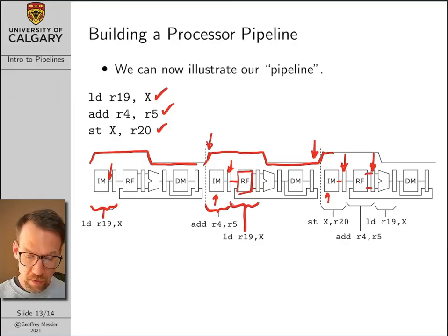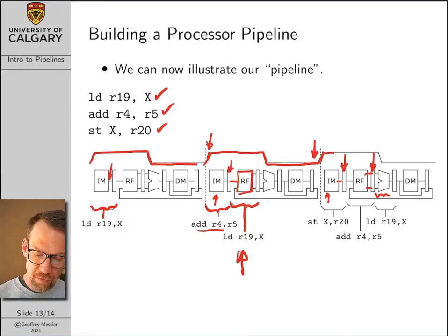So what does this mean? Well, the register values that we read over here for load are now being worked on by the ALU. The instruction memory value for add is now fed forward to the register stage where we're going to fetch the registers required by add. And the instruction memory over here is going to be put to work fetching the machine language for the store command.